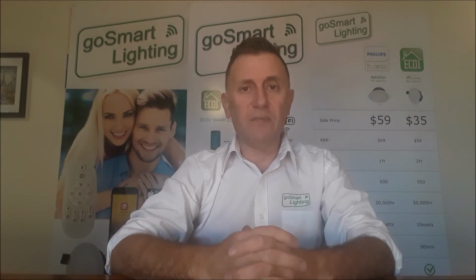You can add more rooms. What's really important here is that you add a lighting control and give it a name, because that name is going to be used later on in scenes. So the more lighting controls that you add to your app, the more control you will have over individual groups of lights. So think about a lighting control as a logical group. Once you use that lighting control within a scene, all those lights associated to that lighting control will operate when you either execute that lighting control in an on or off execution.